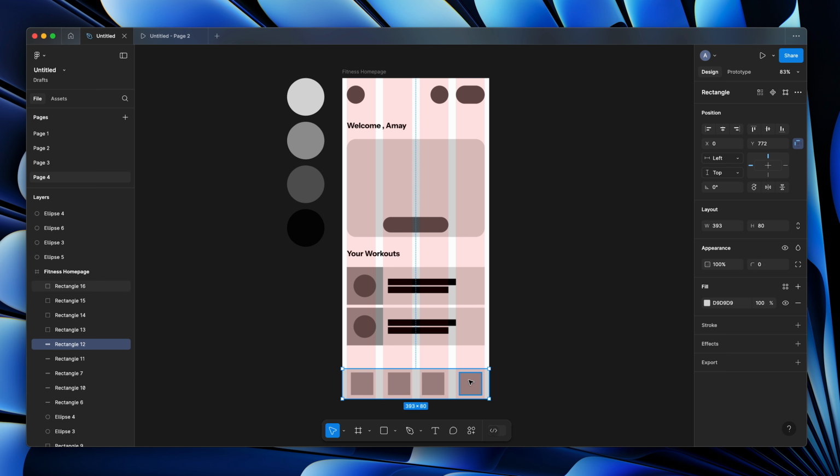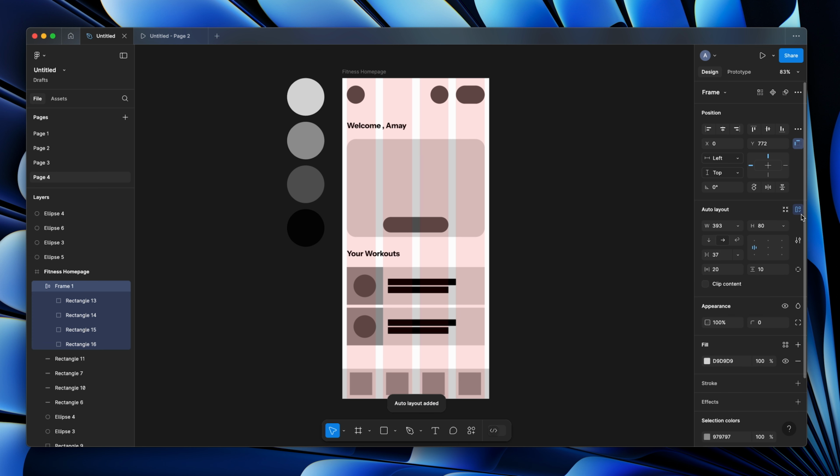And now what I want to show you is a feature of auto layout, just as a glimpse. So what you can do is select all those 5 elements and then press that option, auto layout, and then also you want it to spread in the middle, right? So you press that middle icon. I'll teach you all about auto layout. Just understand what Figma can do and what all opportunities you have in this software that makes your job easier.